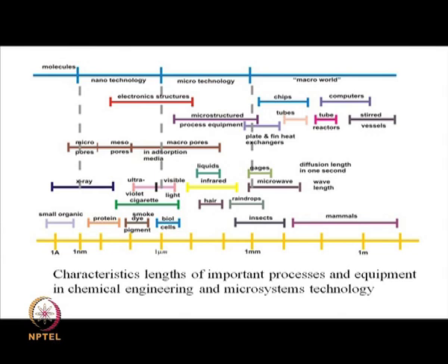An example of this could be that the gravity force is extremely important at the macro scale, whereas the gravity force or body force loses its importance when we go towards the micro scale. Surface tension, which may not be important in a stirred vessel or a reaction taking place in a macro reactor, will play a very important role when you think of flow through a microchannel. So these are some of the basic inherent differences which will govern different forces, different processes, and multi-mode physics when you go from a macro scale to a micro scale.